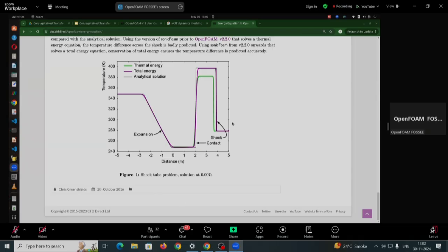If you are comparing Fluent and OpenFOAM, you have to look at the pros and cons. Fluent may be a little faster, and it will also converge. That way it is also very robust. It will give you converged results, and even if you make mistakes in the setup, it will still give you results. That is also true. With OpenFOAM, you have to really know what you're setting, otherwise you get incorrect results.